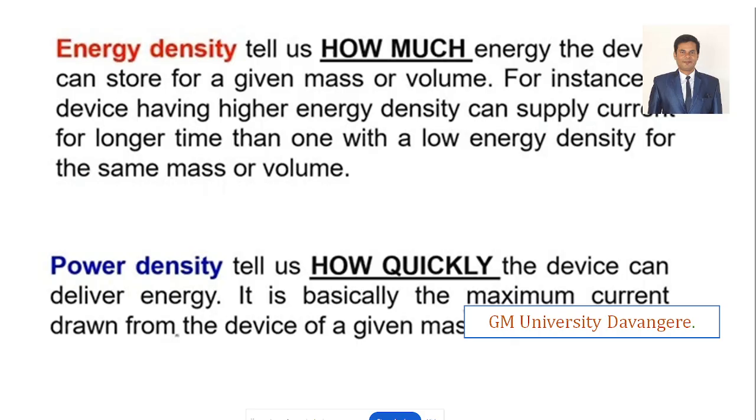When you talk about inductive loads, sometimes reactive power matters a lot. Real and reactive power, these two parameters are very important for the consumption of power where we have inductive loads. You require the real power and you require the reactive power also. If reactive power is less, your inductive loads cannot work. So that's why we have to think more about the reactive power in the transmission lines.